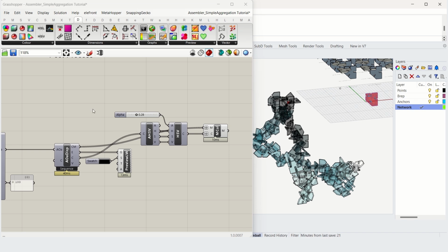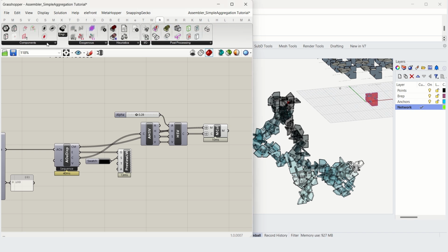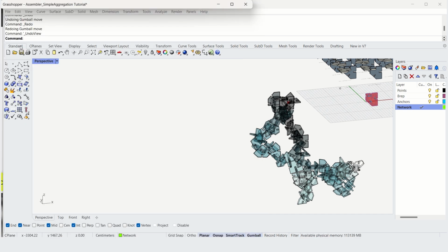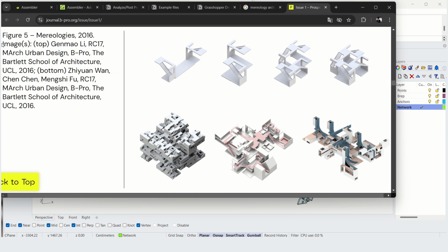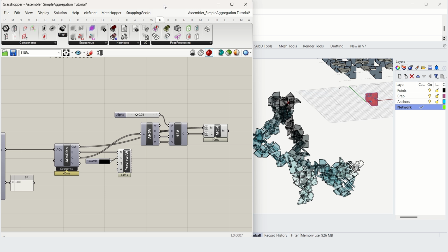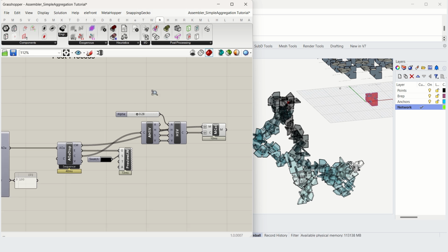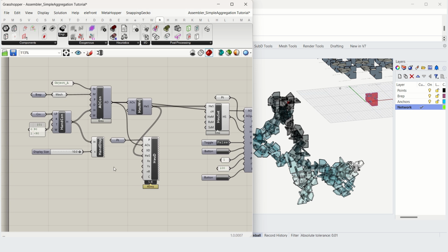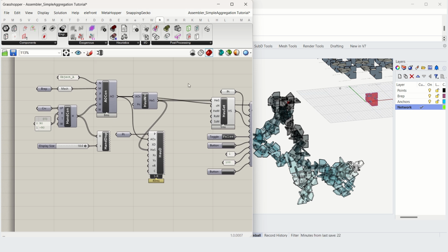This video introduces XData, that is extra data, which is data that can be associated to each element after the simulation has run. Most often in assembler models, this is high-res geometry that has all of the architectural features for visualizing, but which would slow down the engine and aren't needed at that stage. But the XData can be anything: text, geometry, materials, and even a mix of data types. In this example, the associated data will represent a connectivity network that will help identify linkages across pieces.